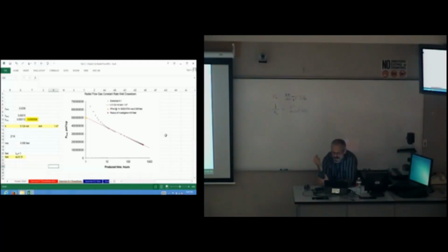The red dot at the very end indicates that we're still in radial flow. In other words, we always use our last time point in our radius of investigation equation, assuming that the last data point is still on infinite acting flow. If it curves away from that, we would use the point at which we're curving away, because that's when we are assuming we're seeing a boundary.